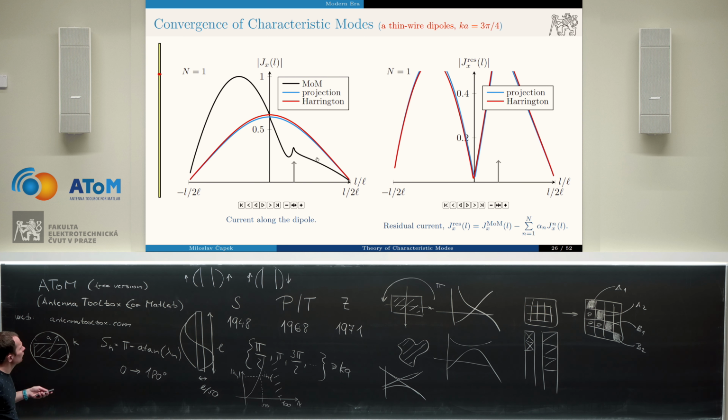Because actually, this is what you have to perform, this derivative, which is equal to this formula. And now, if you consider that lambda n is equal to 0, so you are exactly at self-resonance of the nth mode, it's only this formula. And once again, you can easily compare it with the definition here, which is the definition for Q.